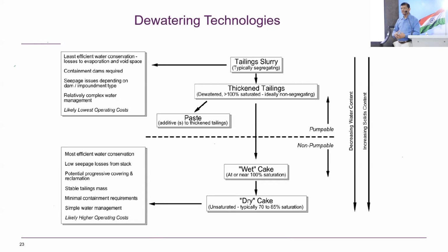But the thing is, these dams are huge, so we do it only on specific locations. We do not do that for the whole dam. That is not viable. So you have to identify the critical areas where you see that slope failures will occur. Then we can do specific measures for that particular area. And mostly the reinforcement is putting berms. Oh, it is called soil reinforcement by putting berms.